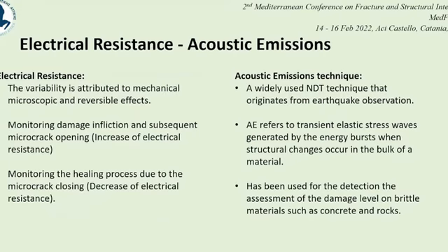For acoustic emissions, it's a widely used surface technique, which originates from the earthquake observation, and they refer to the transient elastic waves, which are generated by the energy burst when structural changes occur in the bulk of material.